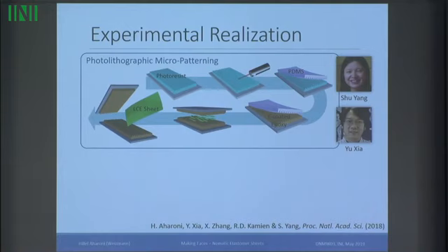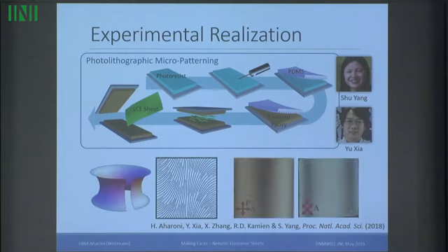They create two molds and coat them with epoxy, and they scratch micron-sized tunnels on the epoxy, and the liquid crystal molecules align along these tunnels. Once you put in all the ingredients for the nematic elastomer sheet between these two molds and you cross-link everything and take it out of the mold, you get a flat sheet that has at every point a director field pointed the way that we wanted it to point.